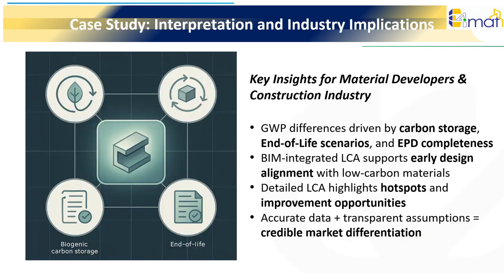This case study shows that LCA results are strongly influenced by three elements: biogenic carbon accounting, end-of-life assumptions, and the quality and completeness of EPD data. For material developers, this underscores the need for transparent, phase-specific information to ensure that their products are assessed consistently across different tools. For the construction sector, BIM-integrated LCA supports faster, early-stage decisions, helping designers identify where low-carbon materials can be adopted without disrupting the project.